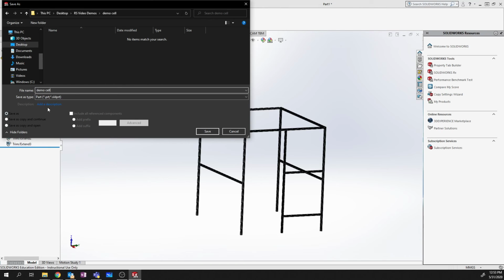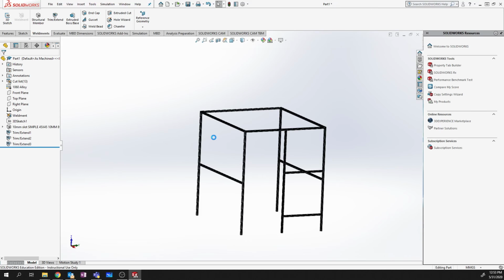Now, keep in mind, you cannot import your solid model file into Robot Studio unless you specifically paid for that option. So instead, what we're going to do is we're just going to make this as a solid part, so it's easy for us to go back, edit, change dimensions, adjust the base, positioning, all of those other different things later on if we need to.